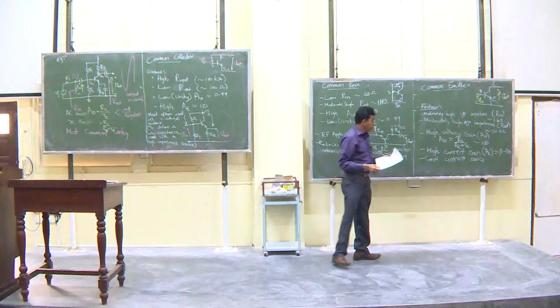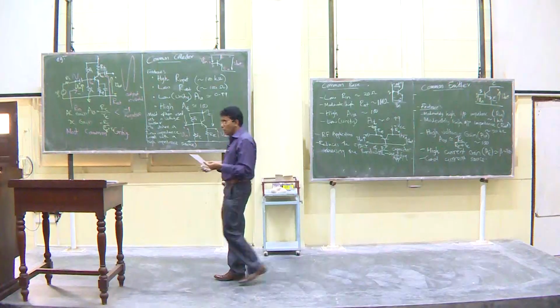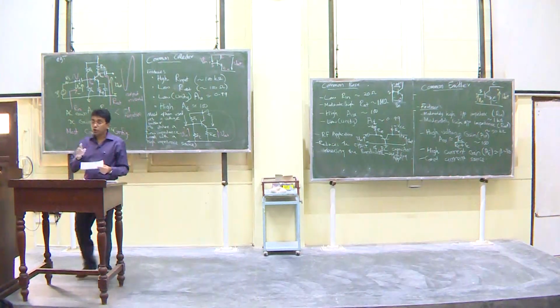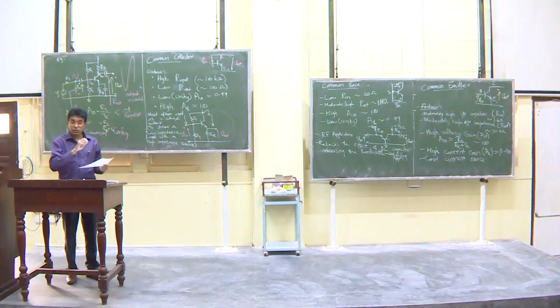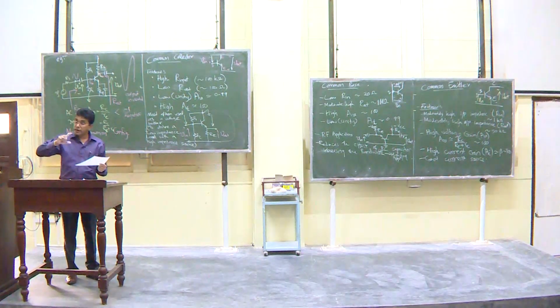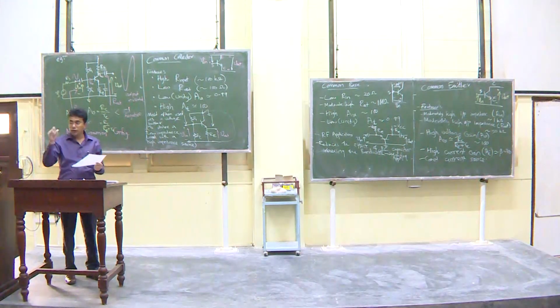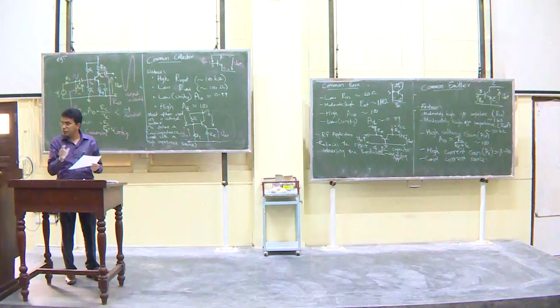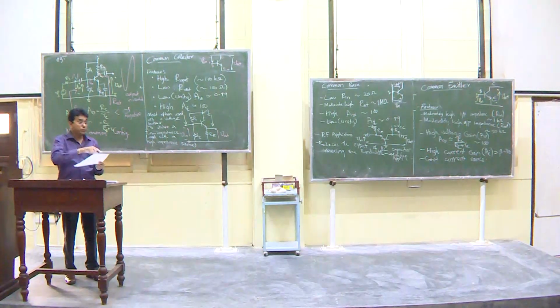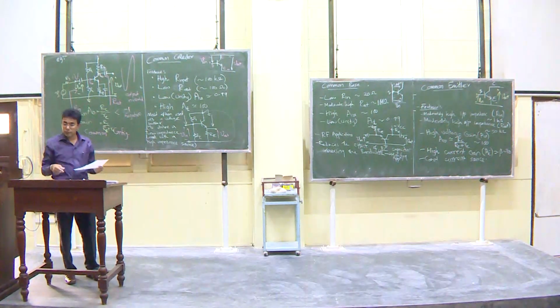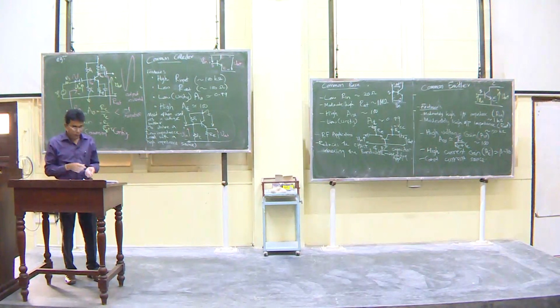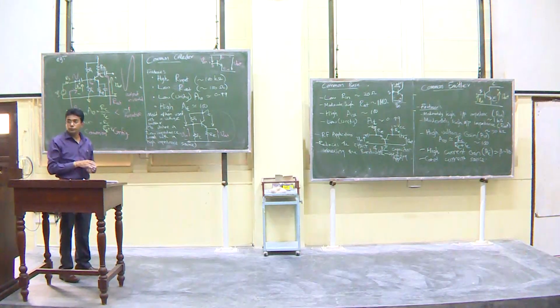So, you can use this as a constant current source. The use of this is you can drive a capacitor using this constant current, so that it can generate a linear ramp signal. I is constant, I equals C dV over dt, so you can obtain the voltage by integrating I over time. A constant integrated over time becomes a ramp. So this is typically what we use it for also.